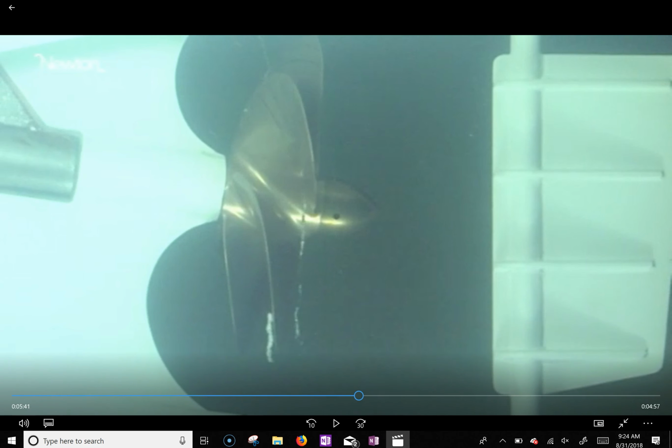As it's spinning, it creates these air bubbles because they're creating low pressure, and they're actually imploding. They're causing little basically explosions or implosions as they go in. Those are really close to the metal, and it causes damage because it's a high pressure wave hitting that. This also occurs in pumps in certain situations because a pump has a propeller. It's spinning around, and it could create low pressure and cause that. So you need to monitor your pumps to make sure that doesn't happen, or if it does happen, figure out how to fix it.